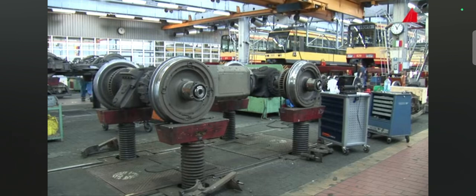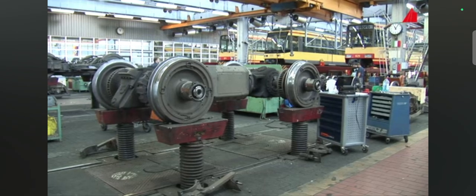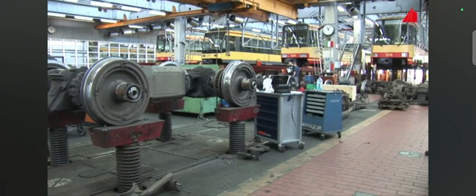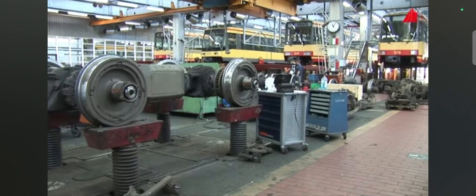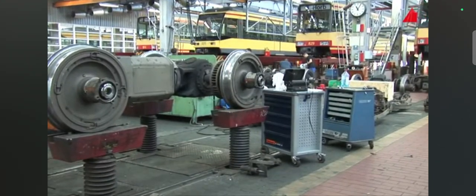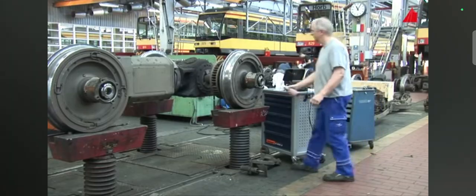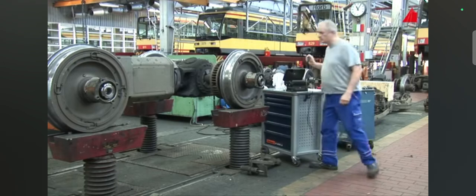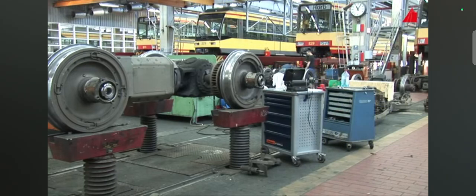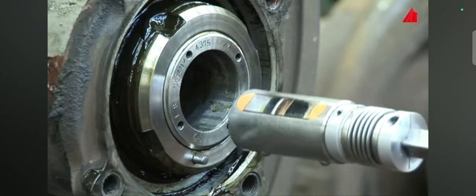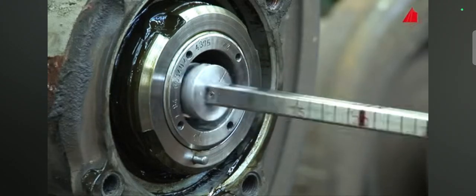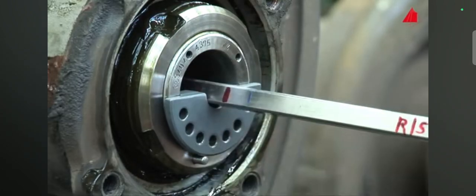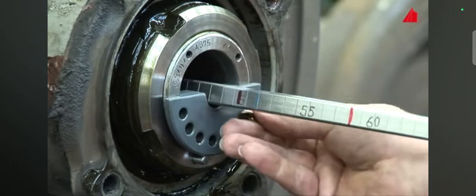This is one of the bogies jacked up to comfortable working height and prepared for ultrasonic inspection. Special attention is given to the wheel axle, among experts known as wheel set axle. It has been designed as a hollow axle. This saves weight and facilitates the ultrasonic examination. The material tester applies a suitable oil as a couplant into the bore of the axle. Now he takes a special probe designed exactly for this purpose, inserts it carefully into the bore with a mount, and evenly spreads out the couplant by turning and pushing. He has accurately marked the most important examination points at the mount.